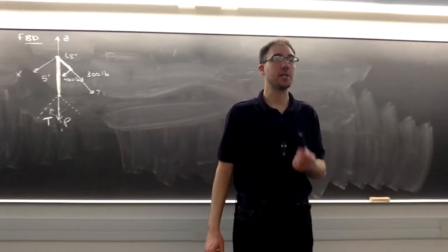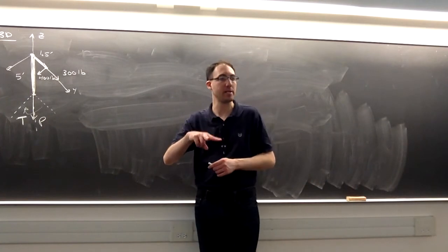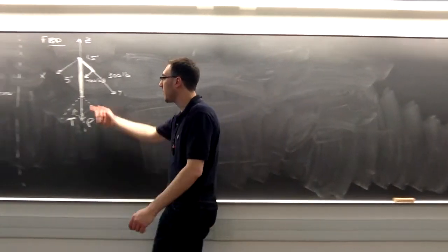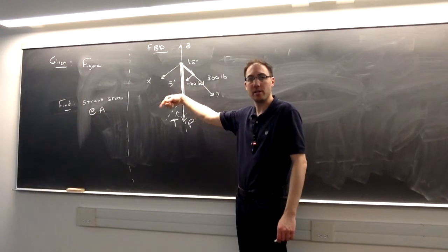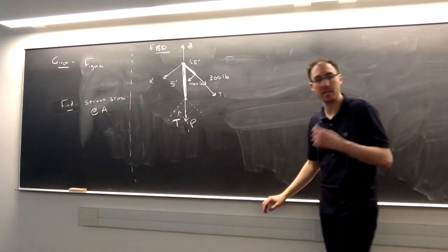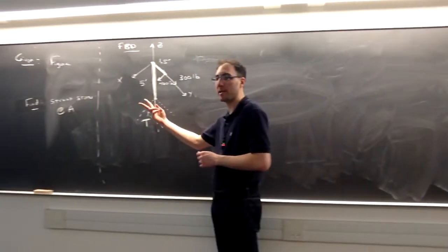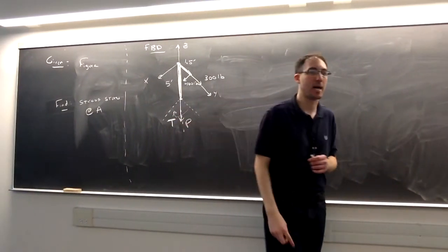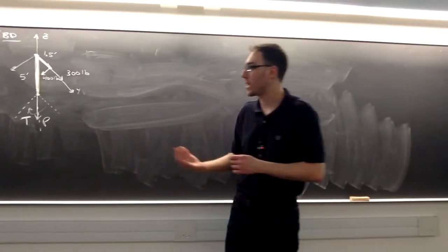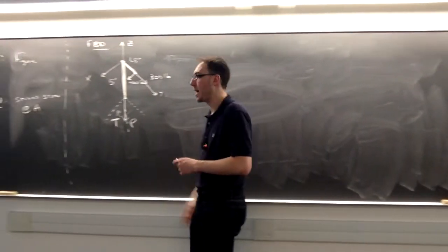We're in 3D, so we're going to have 2 components of shear force. Really it is only a shear force acting in one direction, but we split it into components because mathematically it's easier to solve that way. So I can split it into 2 components that are parallel to that cut surface. For simplicity, I can just use the coordinate system I established here.